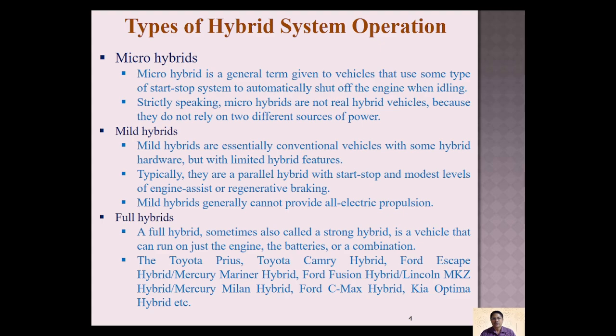This system will shut down the engine during idling and it will start whenever the pedal is pressed by the driver. So this is how this hybrid works. That's why it is called a micro hybrid. This will not power a vehicle in electric form.